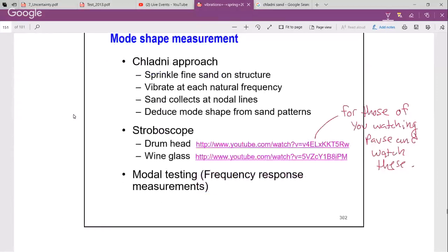All right. So we've also drawn some circles and lines on here. The reason we've done it is because there are going to be different mode shapes. Right now, you see the first mode, the whole thing moving up, and then the whole thing moving down. But then it's going to start doing things like this. There'll be a line here, and then you'll also have ones where some of the circles are going down and some are going up. Keep an eye on that number on the signal generator in the background because that's the actual frequency this is moving at. You wouldn't be able to see it without the strobe light on.